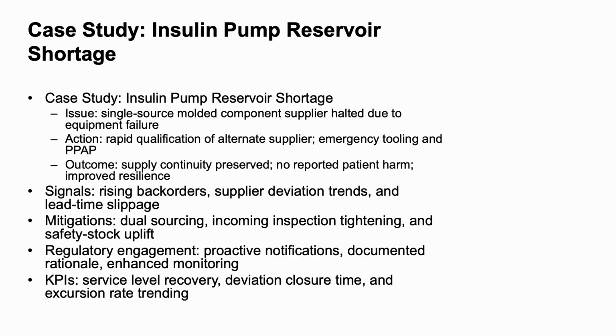The immediate action was to initiate rapid qualification of an alternate supplier previously scouted but not fully approved. Engineering provided drawings and critical to quality (CTQ) characteristics. Quality teams defined a compressed but defensible qualification plan, including material certifications, capability studies on critical dimensions, extractables and leachables assessments, and performance testing in assembled devices. In parallel, the original supplier launched emergency tooling repairs and added shifts.